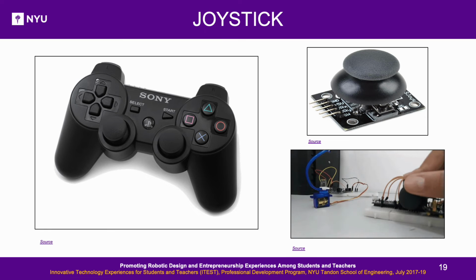Joystick. A joystick is an input device that can be used with Arduino as a gaming console. The joystick consists of 2 mechanically linked potentiometers arranged to capture the horizontal and vertical components of the joystick. Therefore, the resistance of the potentiometer changes independently depending on the joystick position. There is usually a push button that activates when you press the joystick. Joysticks can be used in gaming, robot control, RC cars, drones, etc.